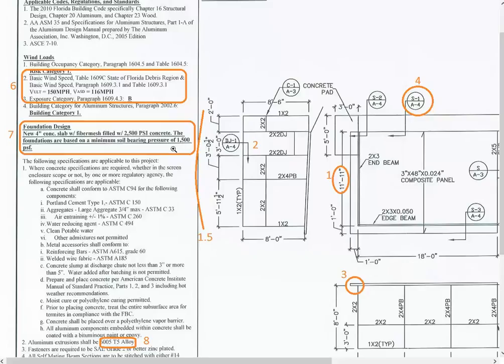If you're building a new building, you're going to have probably a 4-inch concrete slab nominal with a 12-inch footer, probably 5,000 psi concrete or higher, and probably a minimum soil bearing pressure of 5,000. So it's not quite as stringent as it is for a host structure, but it's definitely going to ensure that your patio is staying down there.